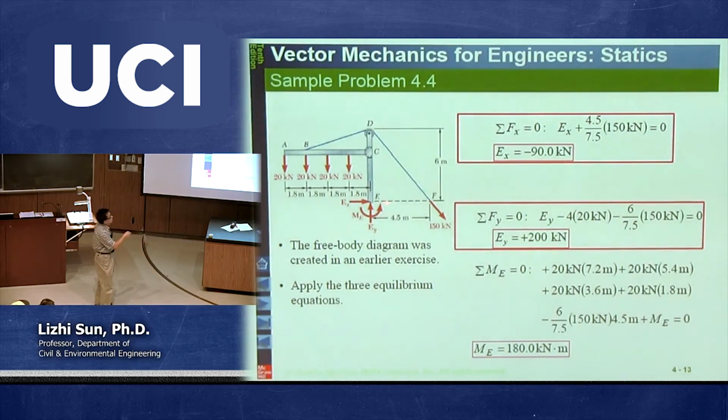We have the moment itself. So what is the moment due to this moment? Then of course you just add this moment. It's called moment E, which is unknown. But this moment is also counterclockwise. That's why you put a positive sign in front, because counterclockwise typically is positive. Okay? So we have considered all the forces on this side, but don't forget, we have one more.